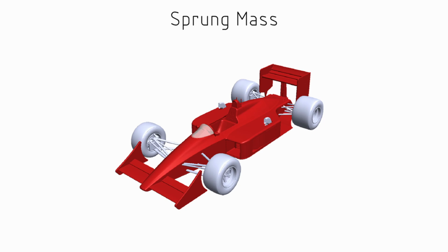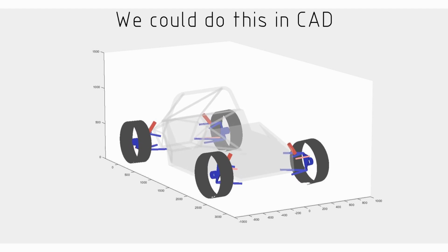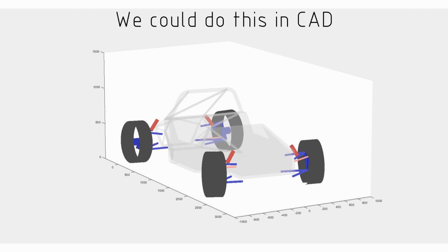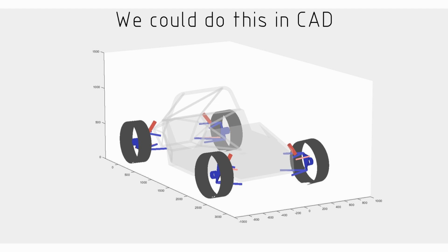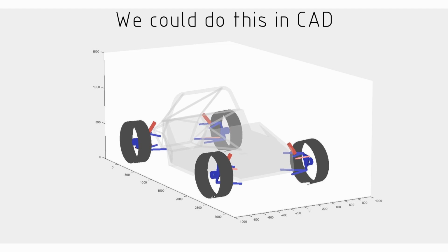If we do it that way in the model, then we can have in our SolidWorks model something that is able to move around. We should be able to move around the sprung masses into various locations and see how the suspension will move as a result of that. Or conversely, it allows us in that top level assembly to move our unsprung masses independent of our chassis and powertrain and move it through the full motion, so the full vertical motions and full steering motions, and we can check for things like clashes of geometry.